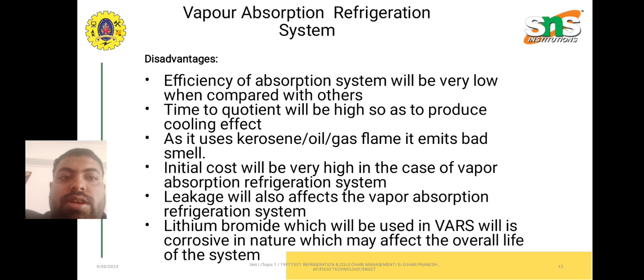Disadvantages. The efficiency of the absorption system is very low when compared with others. Time to produce the cooling effect is high. As it uses kerosene, oil or gas flame, it emits bad smell. Initial cost is very high in the case of vapor absorption refrigeration system. Leakage will also affect the system. Lithium bromide, which is used in VARS, that is vapor absorption, is corrosive in nature and it may affect the overall life of the system.